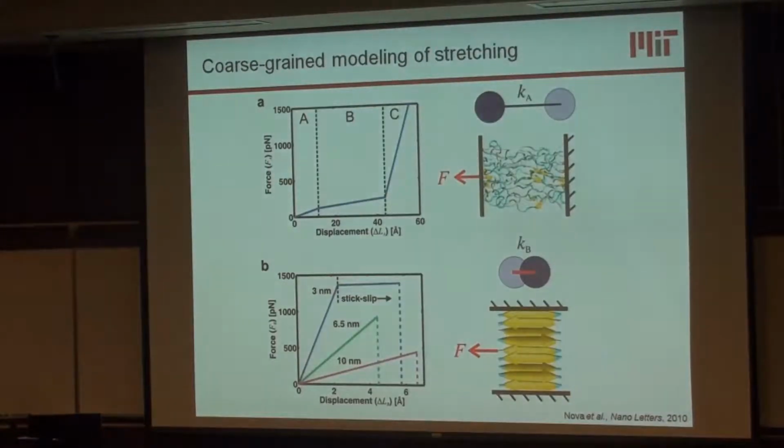And we can run simulations and systematically discuss the mechanical properties of the amorphous region and the beta sheet crystal region. We found the beta sheet crystal region is very sensitive to its size. If the size is small and you pull it, the strand just slides against the other strands, and the force is high. But if you have a very long beta sheet crystal, its deformation will couple with the bending of the entire beta sheet crystal, and it actually becomes weaker during the pulling.